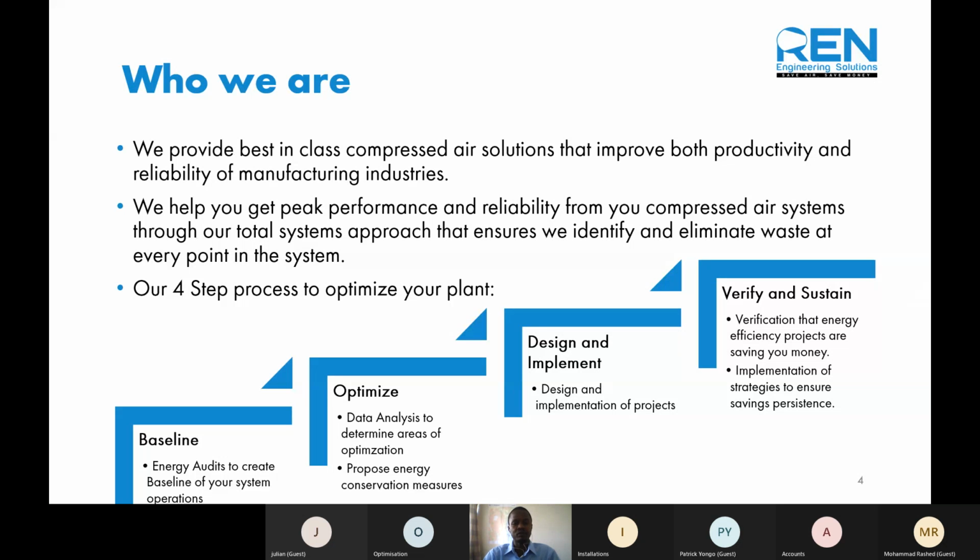That means from the compressor room to the user point. We also use a data-driven approach that starts with the baseline. Think of the baseline as an audit. For energy, we do energy audits, and for quality, we do quality audits.